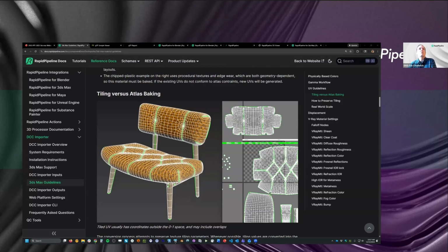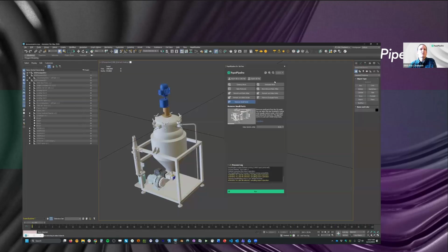But if you say, I want to bake an ambient occlusion texture, so for example, in here, I have bake occlusion map on, that's going to need a second UV set. If you can see the tooltip, it's tiny, but it says basically, yes, it will bake to a second UV set. Or if the whole model has just one UV, then it will just bake into that atlas instead.